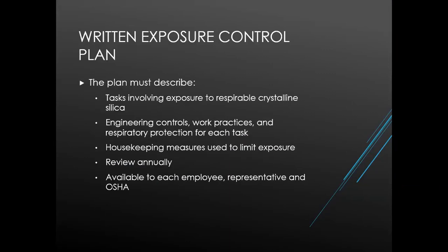If there is silica in the workplace, the employer must have in place a written exposure control plan that addresses a description of the tasks in the workplace that involve exposure to silica, a description of the engineering controls, work practices, and respiratory protection used to limit employee exposure to silica for each task, a description of the housekeeping measures used to limit employee exposure, and the employer must review and evaluate the effectiveness of the written exposure control plan at least annually and update it as necessary. This written plan must be made available to each employee, the employee's designated representatives, and to OSHA.